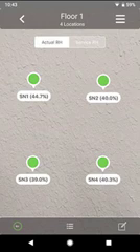At the bottom center, you can select to view the actual RH values or the service RH values as predicted for the service temperature defined for this sensor map, which is set when the sensor map is first created or last edited. The upper left arrow button closes the sensor map and takes you back to the list of all sensor maps for this job. The upper right menu icon takes you to the screen to edit this sensor map's details, such as target RH, service temperature, slab thickness, etc.